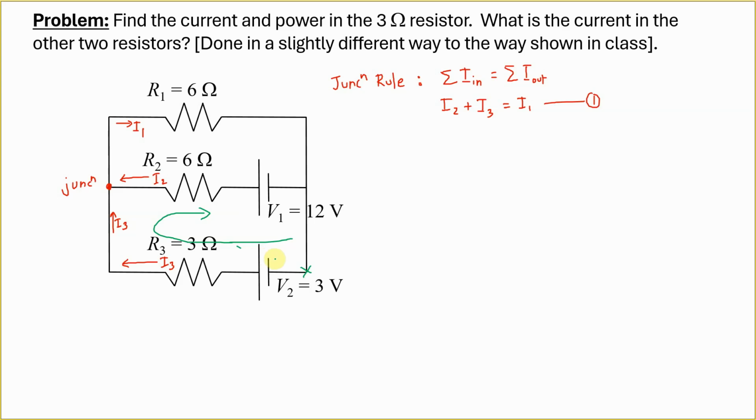So I start walking, right? Let's imagine that I'm walking with a positive charge in my pocket. I'm starting to walk from this X, and I first meet the negative terminal of the battery. And I want to climb this hill and go to the positive terminal. So remember what the electric field was? The electric field is always from positive towards negative. So to make this journey with this positive charge in my pocket, I have to climb a little hill, right? I have to go uphill from negative terminal to positive terminal, opposing the electric field.